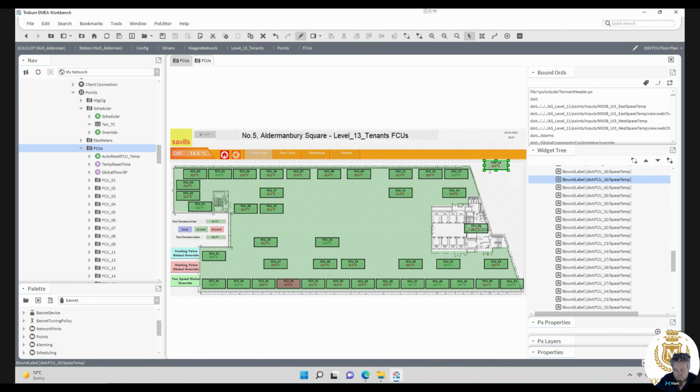So that's one done. The background, which I mentioned when I did 11, that's giving you a colour depending on the temperature. So 18.1 to 24 is a green background. Under 18, 0 to 18 is a purple, and 24 to 40. I'm going to just put greater than 24.1 degrees, it goes red. That fan coil's offline by the looks of it.